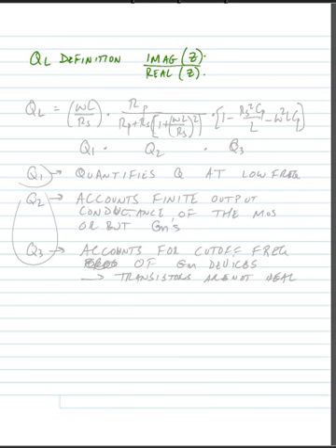So if we take this definition of quality factor for the prior circuit and isolate the imaginary part and real part, we would find that the quality factor of our circuit would be equal to omega L over RS times RP divided by RP plus RS, times 1 plus (omega L over RS) squared, times 1 minus RS squared times CP over L minus omega squared L CP.